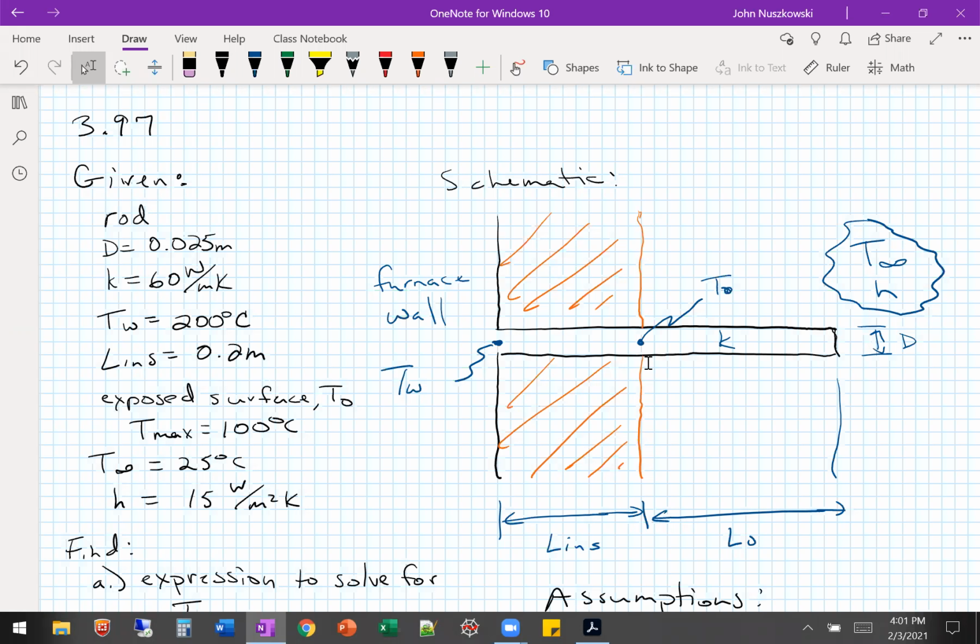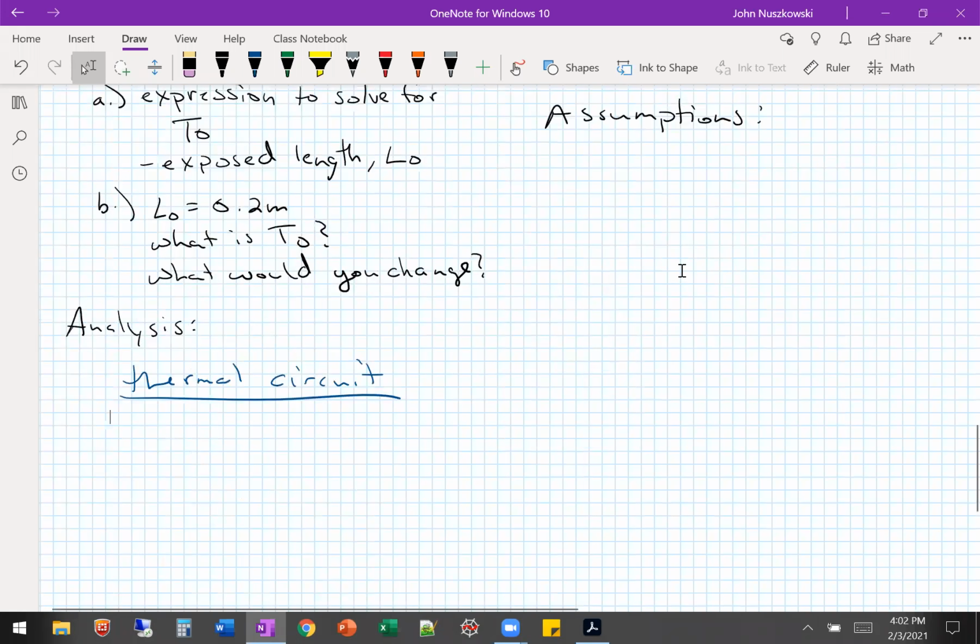It's conduction between those two points. Yeah, so it's purely conduction. There's no convection going on. You don't really have to think of it as a fin. It's just conduction in 1D. There's no combined conduction-convection of a fin. All right, so that takes us as one resistor. So we add the temperature of the wall, TO, and then we have our conduction.